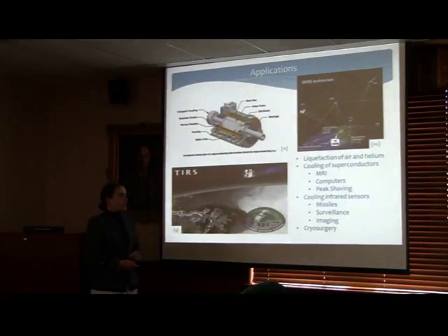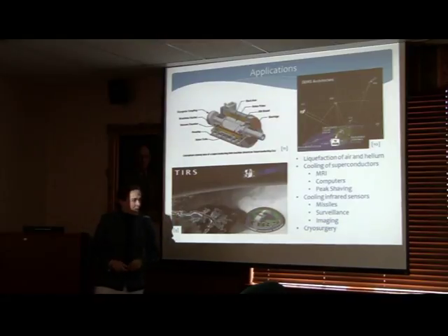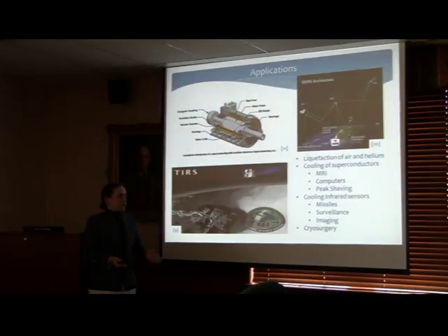So applications, as I said before, liquefaction of air and helium. Pulse tube cryocoolers can also be used terrestrially for the cooling of superconductors for things like MRI machines, computers, and peak shaving. And then mainly what I really wanted to look at, they have a huge application in the field of cooling infrared sensors.